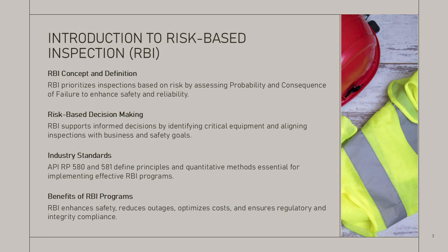Rather than applying uniform inspection intervals to all assets, RBI recognizes that different equipment items have varying levels of risk depending on factors such as operating conditions, materials of construction, corrosion mechanisms, and process hazards. This risk-based philosophy is especially important in complex process industries such as oil and gas, petrochemical, and refining operations.